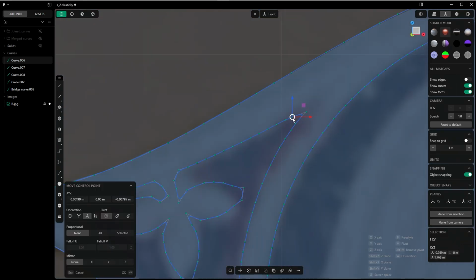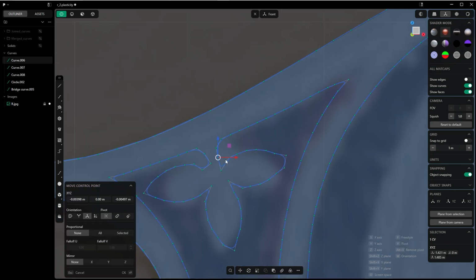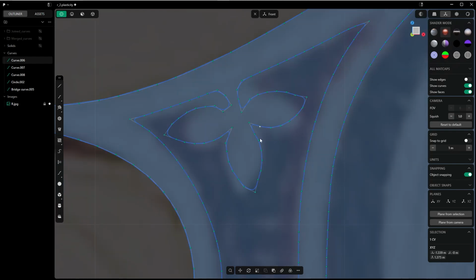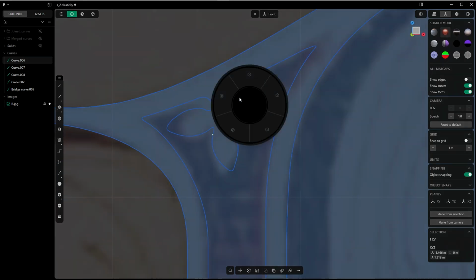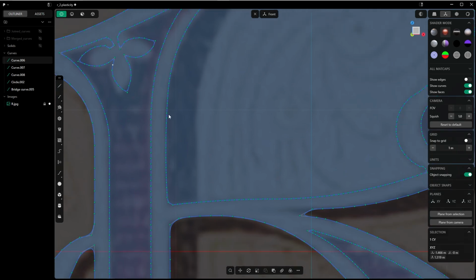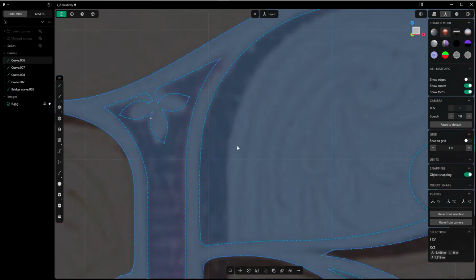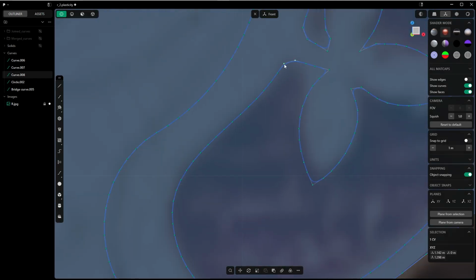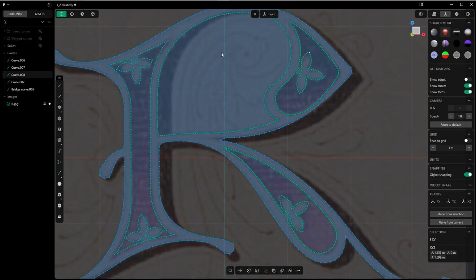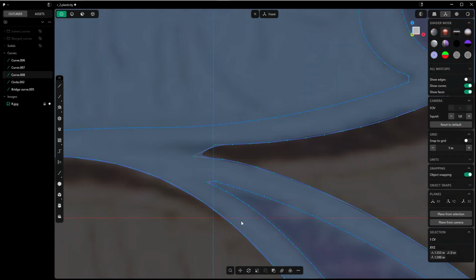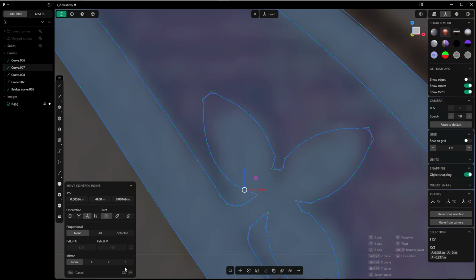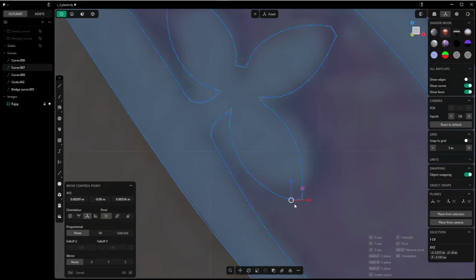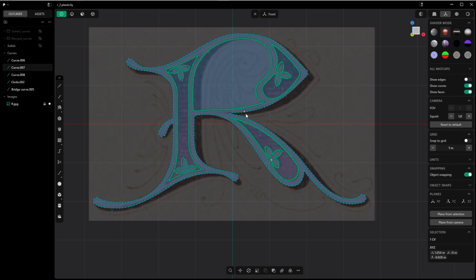Here you can see as soon as you drag the point onto the curve, the shape looks better, the curvature. I hope that makes sense. So always check in edge mode also without being distracted by the control points. Okay, this one is also okay. Continue with this one. Okay, now we have made all these parts, so this is the last one. I think we are finished with the rebuilding part and the fixing of the rebuilt curves.